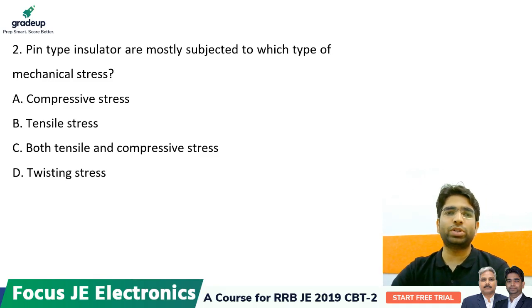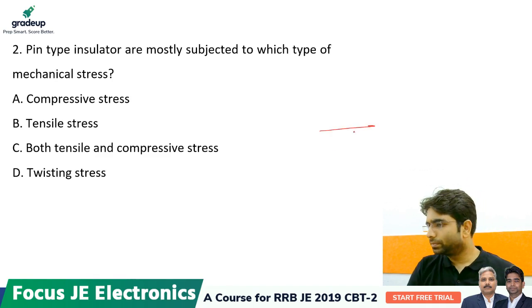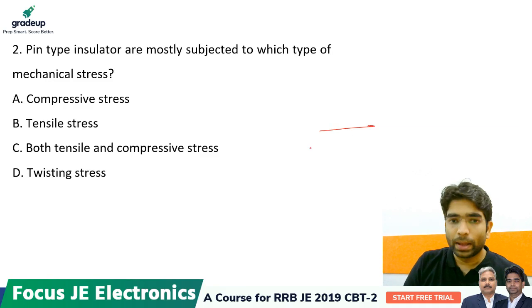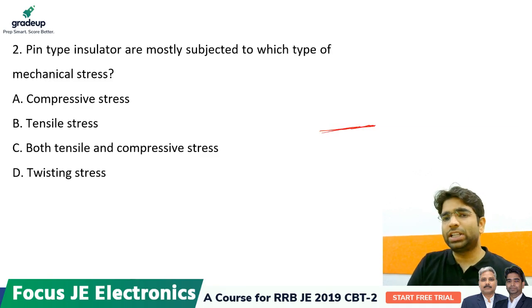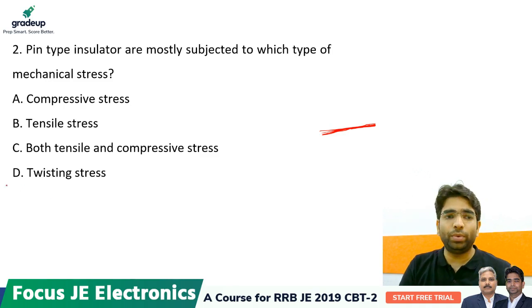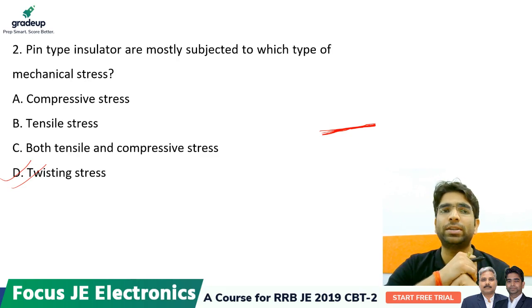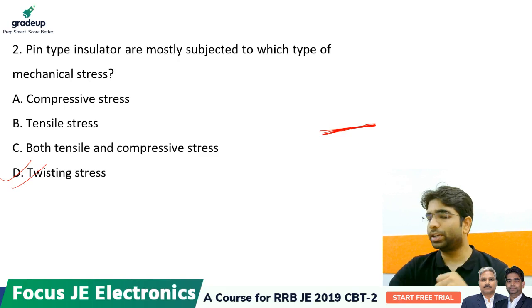Pin type insulator is mostly subjected to which type of mechanical stress? Pin type means that the insulation is very thin. If it is a very thin insulation, then it can be more susceptible to twisting stress. If you twist, it will break. So pin type insulator is mostly subjected to twisting stress.